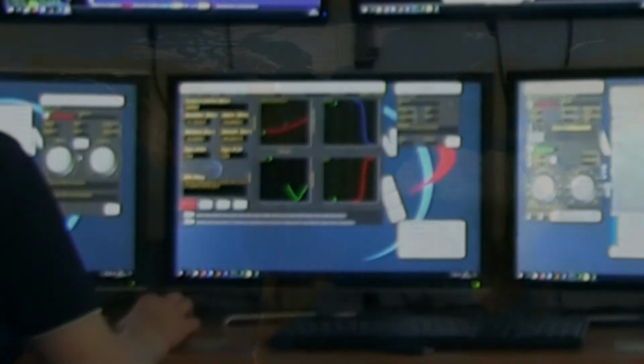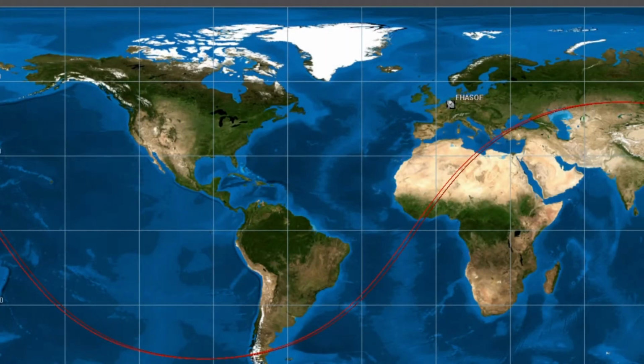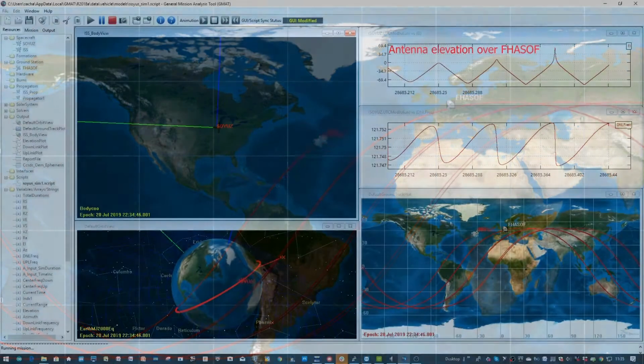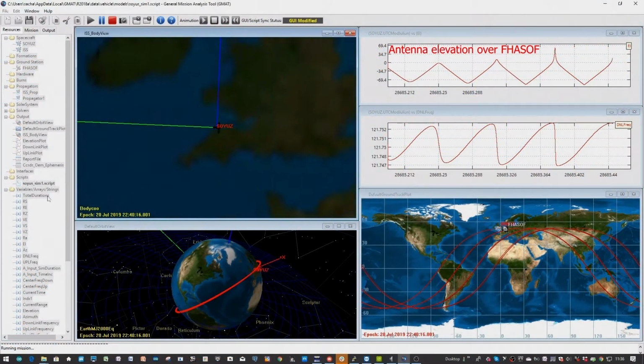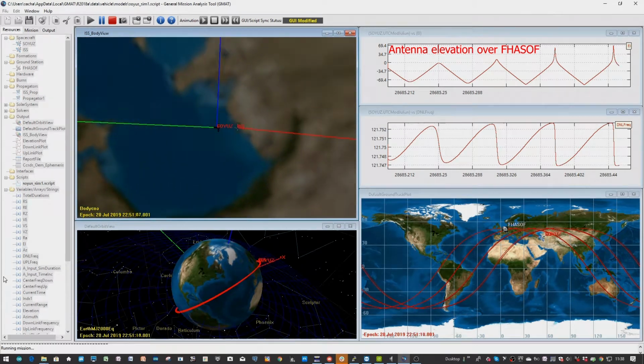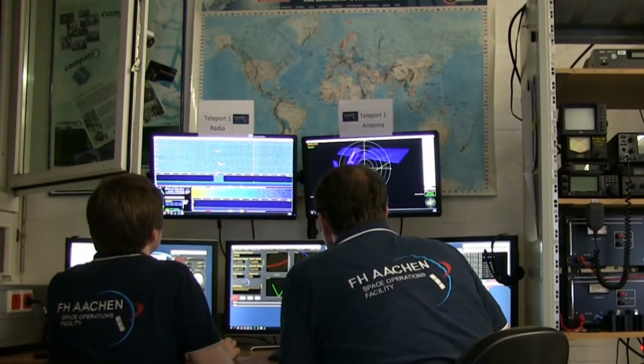From social media and NASA TV, we knew the orbit insertion time and we verified the location of the ISS at that time using the TLEs for the phasing angle. So David and I tried to eyeball the azimuth and elevation, and I simulated the passes over Aachen using GMAT, an astrodynamic simulator, to generate CCSDS ephemeris files for the antenna pointing and the Doppler shift.